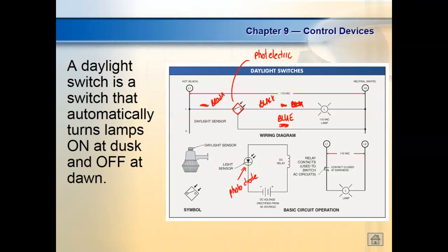DC in control circuits is extremely popular because these guys are computers, electronic devices, they work off of DC. That means I have to go from AC to DC to run these things, right? You understand that? I mean, inside. So the inside and outside would be different. So 24-volt DC is pretty much the standard for control circuits.